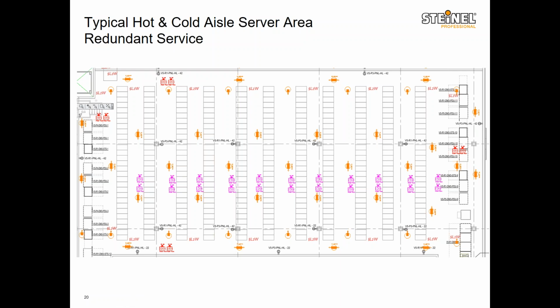So somebody opens the door, they step in, sensor sees them, it won't turn the lights on until somebody hits the switch. They hit the switch and then the lights will be on as long as they're occupying that space. And then after they leave, if they fail to switch the lights off, the sensor will time out and turn the lights off for them in that hot aisle. Again, the hot aisle is not used as often and is an isolated area. So note the design difference.